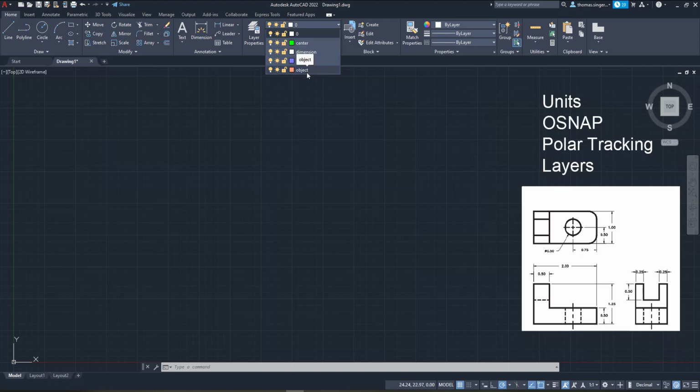So we're going to go ahead and draw the first shape, which is the front view in our drawing. And so we'll get this started and we'll wrap up the video here shortly, just so you can see how to create the drawings. So we start the object layer, we'll choose the line, and again we just want to pick a specific location. Doesn't matter where you pick to start, and we left mouse click and anchor it, and now we've got to draw a line.